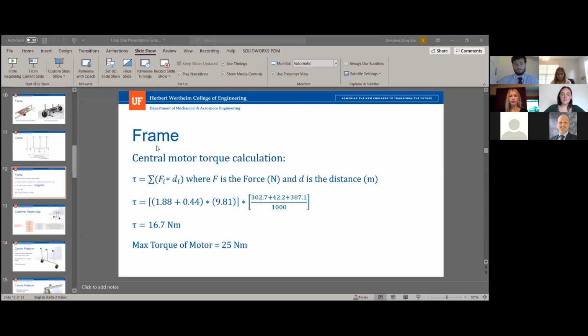So is this torque the actual torque of the motor as in spinning the assembly, or is this the torque of the wind blowing on the mirrors trying to bend this backwards, sort of applying torque to the shaft out of the axis that it's intended to rotate? So 16.7. Oh, no, go ahead. This is the torque required. This 16.7 Newton meters is the torque required to move it without wind. The max torque there is limited not by the motor but by the gearbox. It's a 100-to-1 gear ratio on that planetary gearbox, and planetary gearboxes don't have the strongest of gears in them. So that's regulated by how much force the gearbox can take.